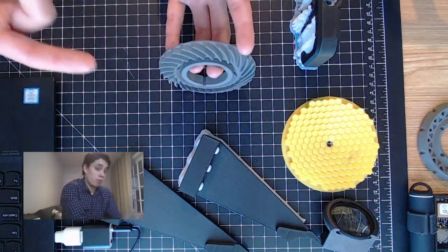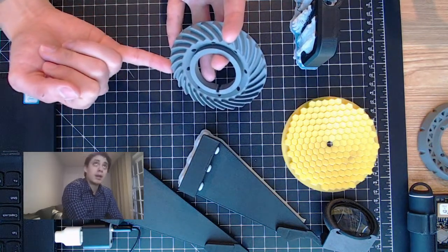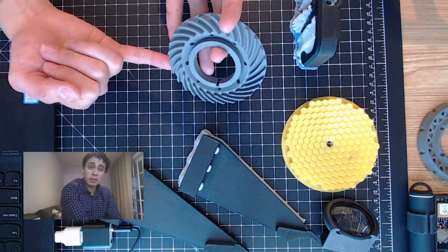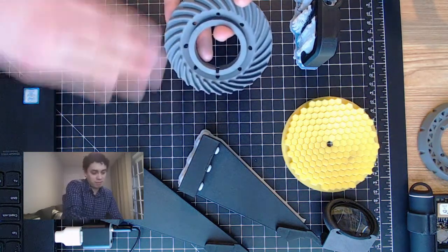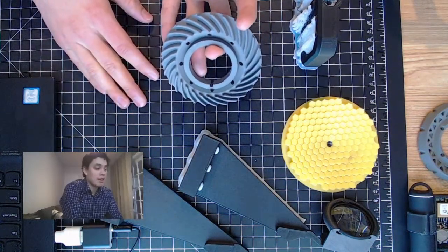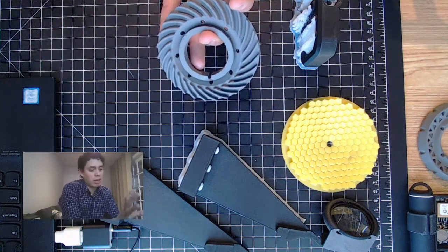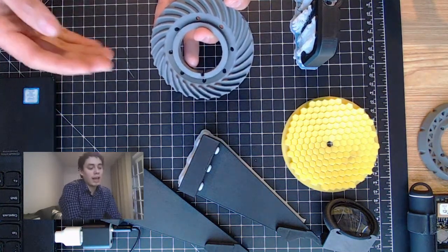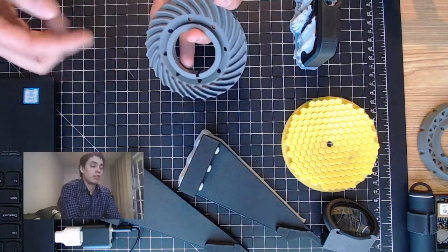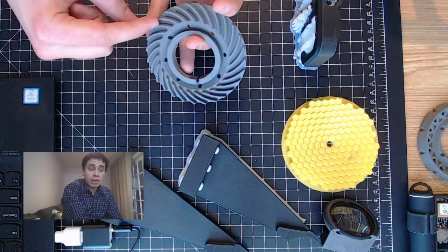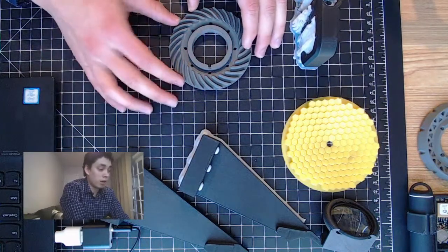Now, the compromise with that is that I would then have an uneven distribution of the layers, I would say. You can imagine how, by splitting this object this way instead of flat against its back, the layers will, I would assume, this is without particular testing in mind, be more likely to shear amongst themselves depending on the way that I apply the force here, right? So it all changes depending on the part that you're trying to print.